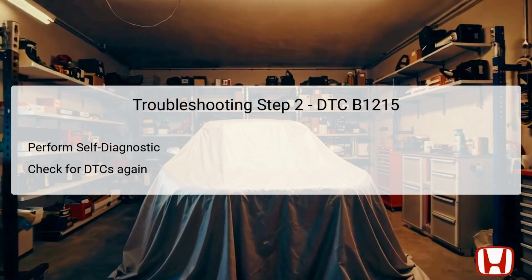The second step involves conducting the self-diagnostic function using either the HDS or the climate control unit. This diagnostic test evaluates the system's functionality and identifies any potential faults within the recirculation control motor circuit and related components.